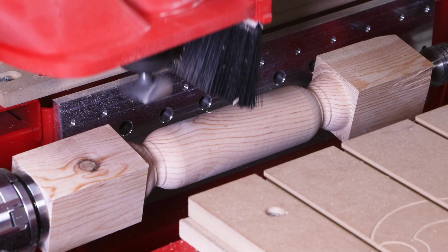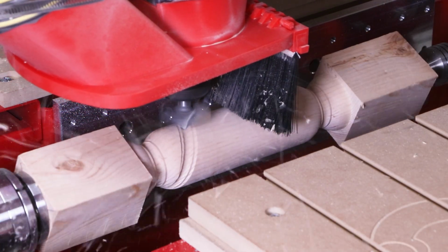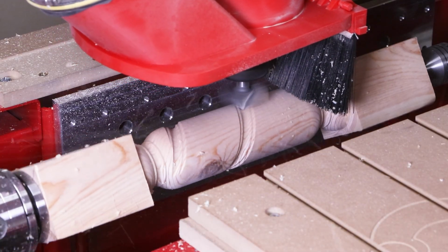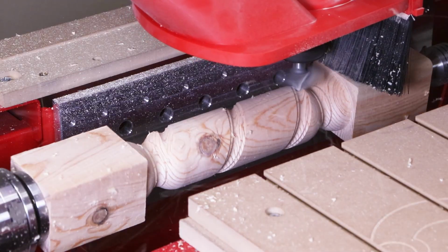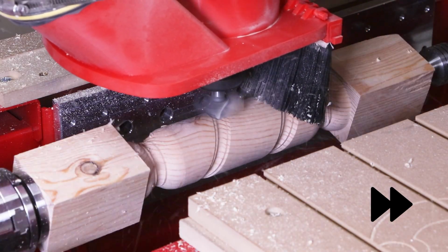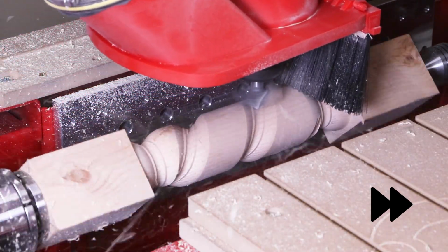Just like other spiral toolpaths, it comes to the starting position and plunges for our first roughing pass and travels down the stock while rotating. Now this is going to take 4 passes for this cutter because it has to plunge deeper than the other tool. But we can see that the pitch, the distance it travels per rotation, is leaving that flat gap left over for the core box cutter.